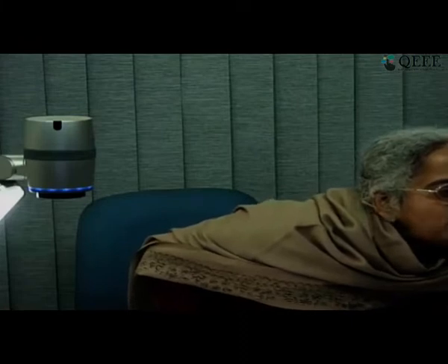Clearly. Suppose we want 100 volts by 400 volts 1 kVA transformer, then N1 by N2 is 1 by 4. We can choose any set of number of turns in the transformer which gives the ratio 1 by 4. But which value is better preferred? It depends upon whether you are looking at the size of the transformer in terms of if it is a 1 kVA transformer, right? And whether it is at 50 Hertz or 100 Hertz or 4 kilohertz, all those things matter, because that will decide basically how much is the area of cross section of the core.